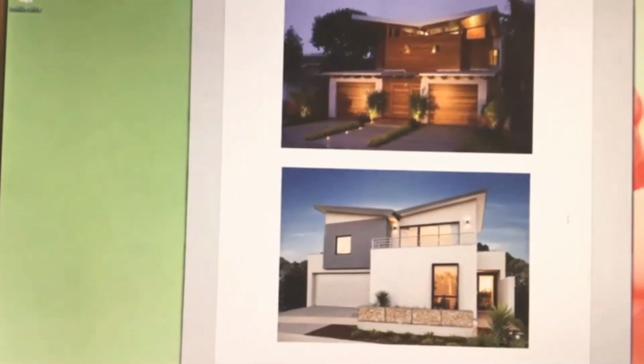Okay, great. So when you look at these roofs, my first thought was the water is going to just run straight to the middle, but that is the point, to collect water. So that's one of the main pros, is that you can collect water and use it. So this would lend well to a green home or off the grid home where you were going to have your own water source. It's also very wind resistant. And on the sides of the home where the roof is higher, you can have larger windows and higher ceilings. But as we said, the water runs to the middle, so drainage can be a problem, and they are expensive to build.